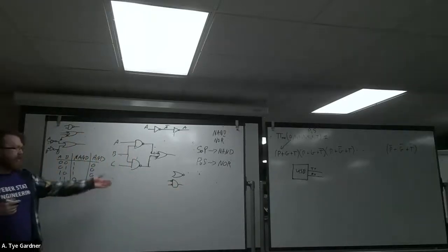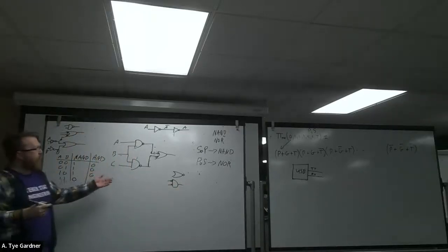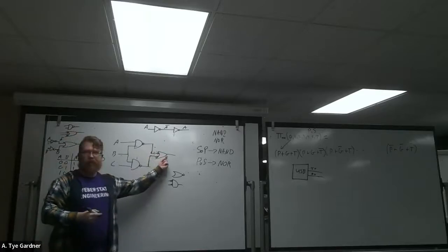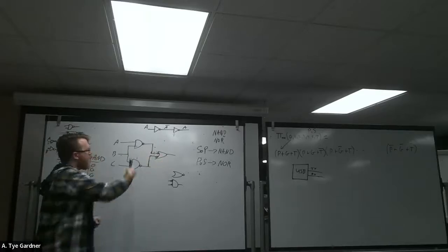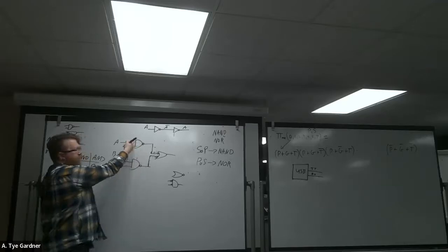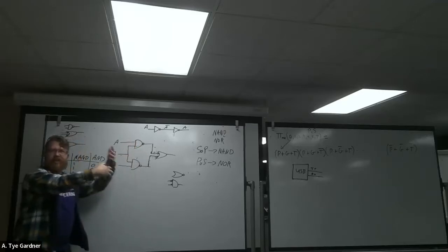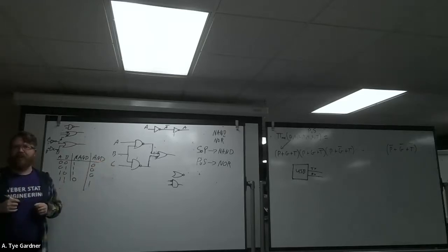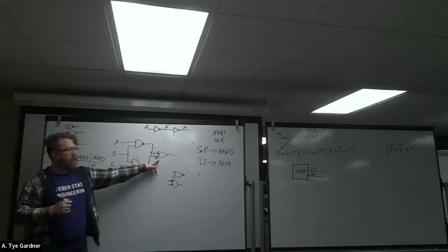Right, that's all this is saying. And so you can do a thing where I could push these through and make that a NOR, and then push these through, and then, well, then it looks like an OR with inverters, and then I would detach those inverters and I would have a NOR circuit. Okay, so this one on the far right, that's a NOR, not a NAND.